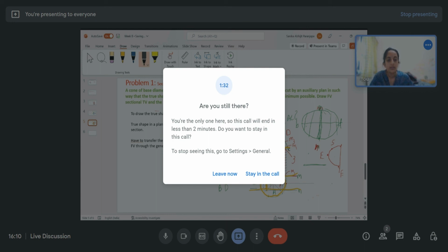From all the construction that we have done, you already got the point B and D. You have got point M and N, which you can trace here, all the points from here to here. And those points you will trace directly on this plane. And all this ruckus, why we did it? To get the minor axis, which is 40 mm. So you know that this will be 40 mm, and from this thing you will get the major axis also, and you will get the points here, this length from this line you will get from the front view.